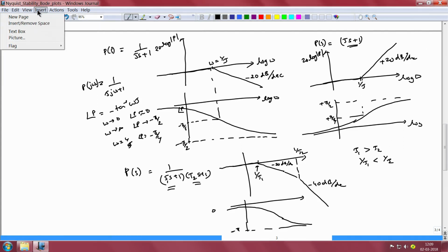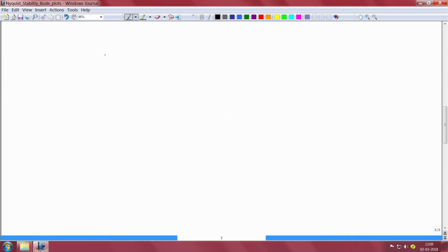possibility for the structure of a second order system, and that is when its poles are complex. So a second order system whose poles are complex can be written out in this particular form: s square plus 2 zeta omega n s plus omega n square, and for a structure of this kind where zeta is less than 1.